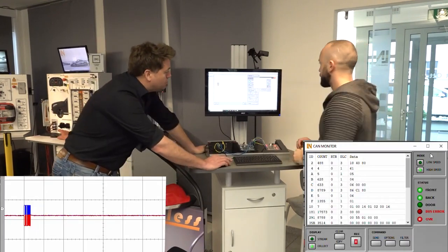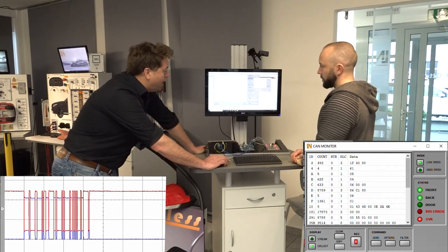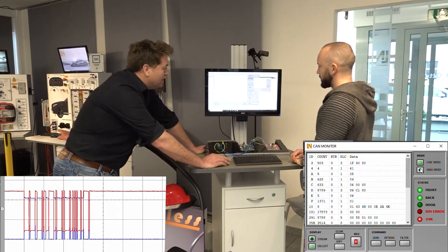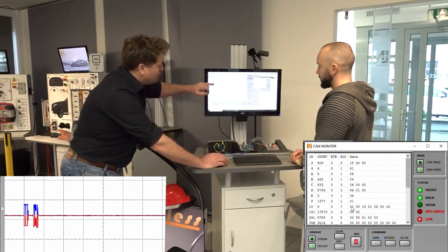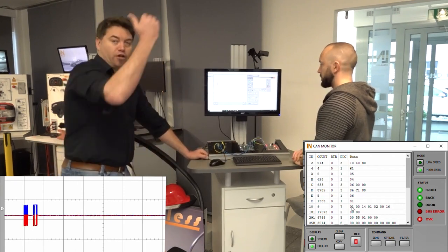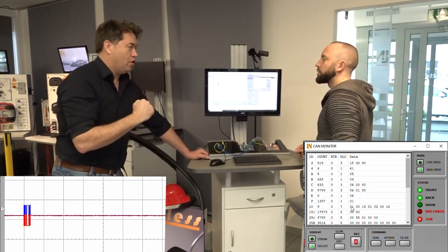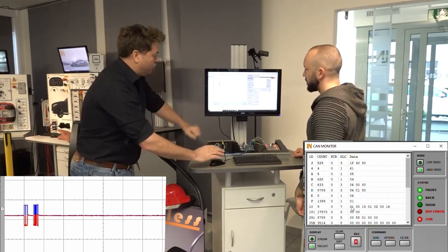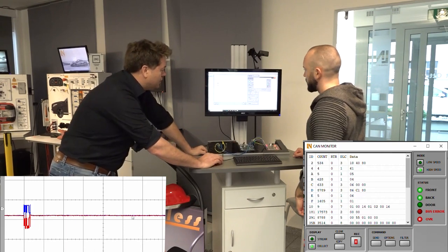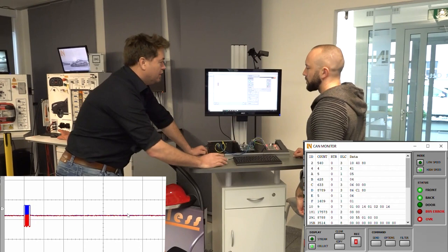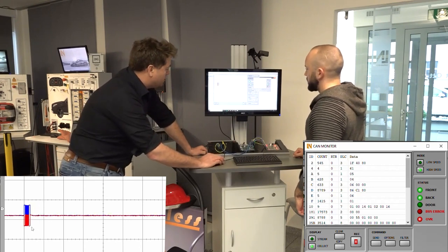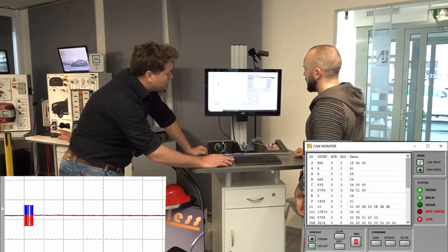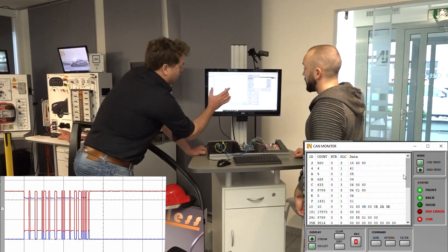Exactly. So we can actually switch between the two now, and you can see how it's same but different. So we've got two signals. I'll switch to high speed, and now what's interesting is high speed is still trying to go higher, low speed is still trying to go low. Yes. But instead of having the difference between them, now the two are at about 2.5 volts together. So they're in the system here and they're going away from each other. And we can see here that the same message that we've seen before is now occurring in a much smaller time. So that's one message right there.